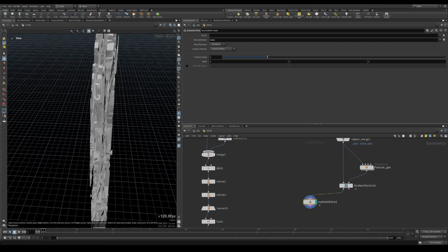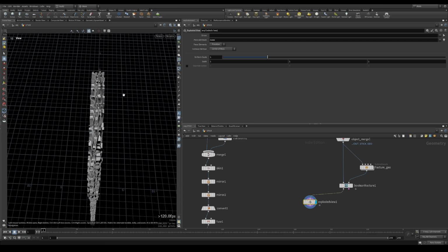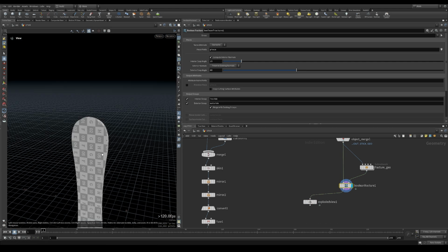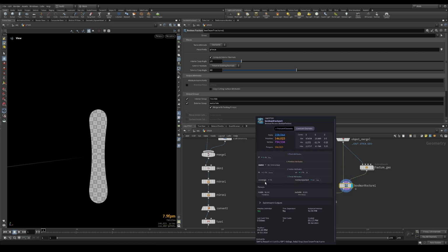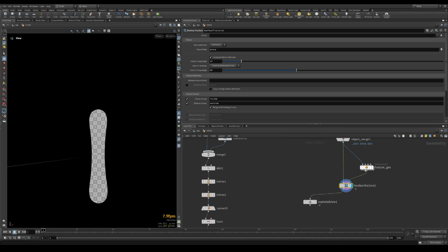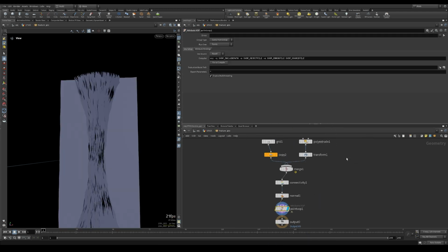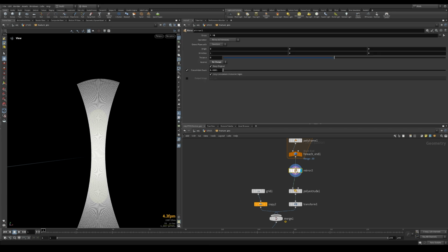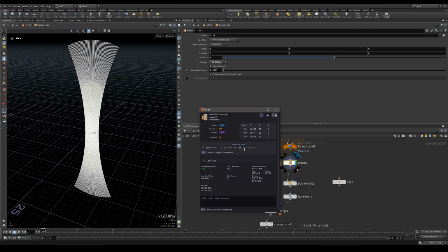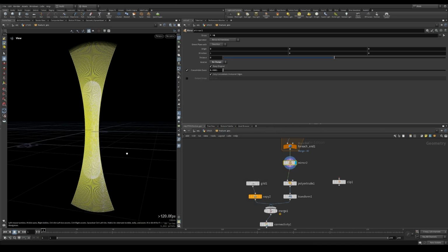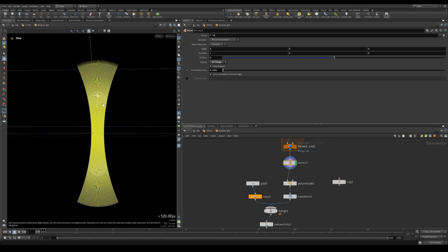And now we have pieces also on the depth of the stick. But when it will be the time of animation, I want the stick pieces to follow the up vector that we calculated, which we have now lost with the fracturing. So we want to go back inside the subnetwork, and here after the mirror, after the loop, we want to branch out first with a clip node, because if we examine the up vector, you can see that everything is going up.